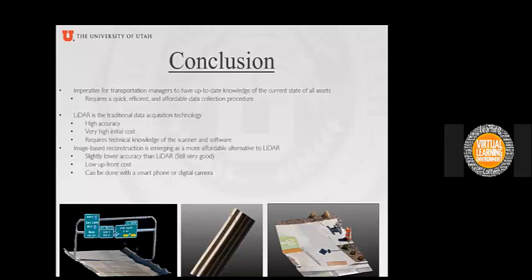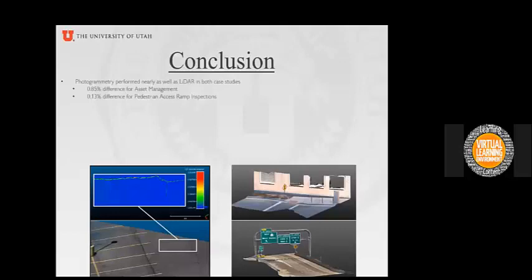Photogrammetry performed nearly as well as LiDAR in both case studies. There was only a 0.85% difference between the technologies for asset management and a 0.13% difference for pedestrian access ramp inspections.